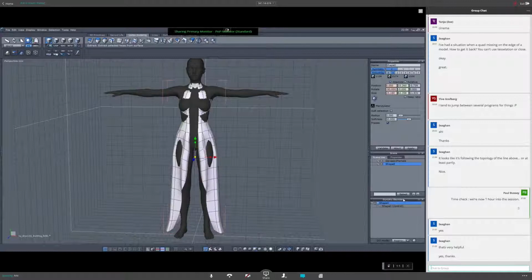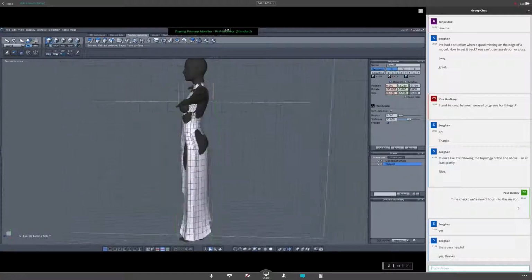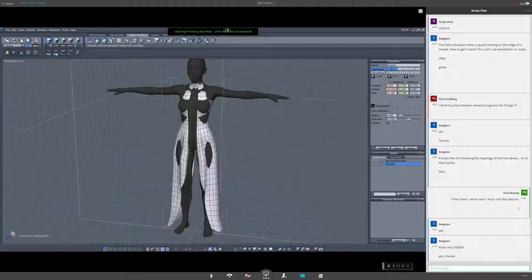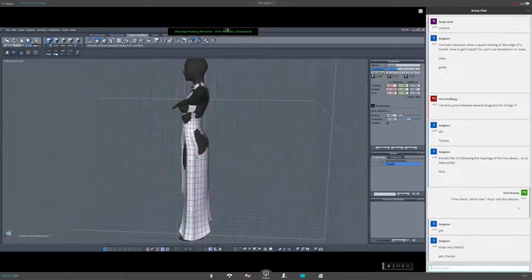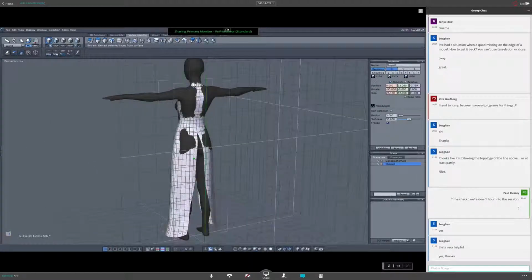You do this by going down here into the dynamic geometry tab and then click on this little lightning symbol, and you see the density has changed. It has retained the new shape, but it has divided each existing polygon by 4. So for each of the original polygons, you now have 4. This was one polygon. This was one polygon, and so on. But you also notice that the dress doesn't fit anymore because with more definition, it pulled a few polygons back inward and pushed a few outward, so you have to fit this.